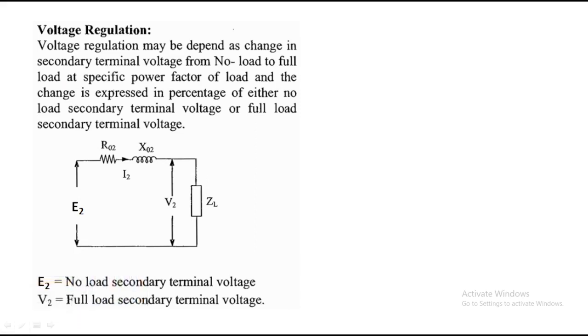So from no load to full load at a specific power factor of load, and the change is expressed in percentage of either no load secondary terminal voltage or full load secondary terminal voltage. This is the equivalent circuit referred to secondary. With respect to change in load only, we get the change in terminal voltage, because with the load changes, obviously the secondary current changes, and the secondary terminal voltage changes.